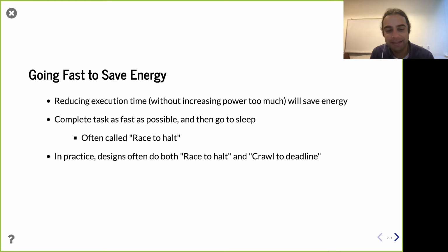And so sleeping for milliseconds is actually well worthwhile. The same thing's true for the radio chatter, right? If your smartphone is sending stuff to the radio, when it's talking to the cell tower, it has negotiated that my next time to transmit is this many milliseconds away. Your cell antenna is actually going to turn off for that time period because I'm not going to be transmitting, and shouldn't be expecting to receive anything. So in a mobile device, for battery life to be anything useful, it's mostly turned off and just turning on for really small bursts, either to render the next frame of a video or to talk to a cell tower, right?